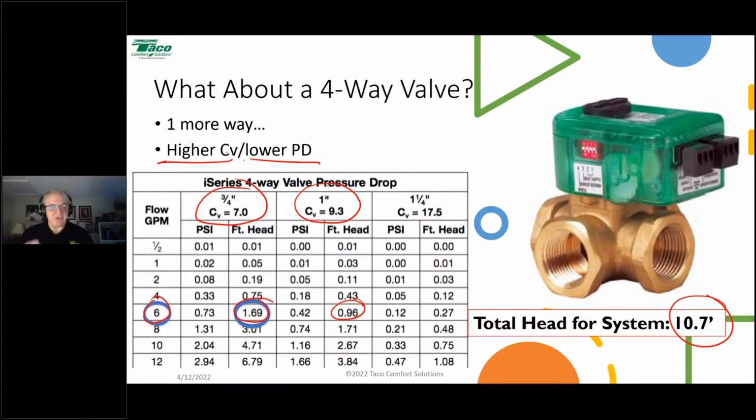What is this valve going to do? It's going to start to open to allow more hot water in to get the temperature up to 120. Really big valve, going to have really big movements. So we're going to allow a lot of hot water in a hurry. So maybe that water temperature bolts up to 140 real quick, and the valve goes, oh, that's too hot. I'm going to start to squeeze it off.